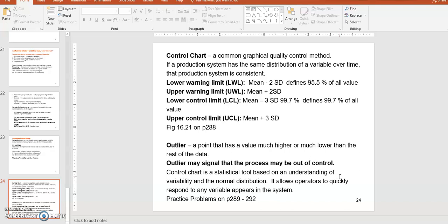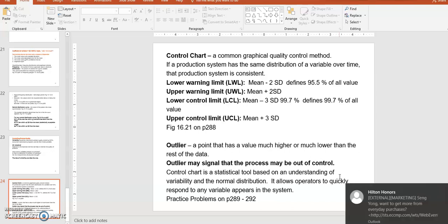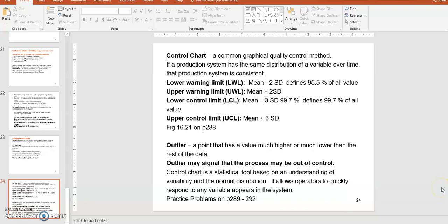Six Sigma, probably you heard that if you already took the class BIOT 102. There should not be any deviations. It's a 6 Sigma, very small deviation, which will be really good if you can make that, right? And control chart everything should fall in within the control. So lower warning limit, upper warning limit, hopefully your values would not go over those. Okay, lower control limit. So your control chart should show those maximum or minimum limits, and everything should fall between.